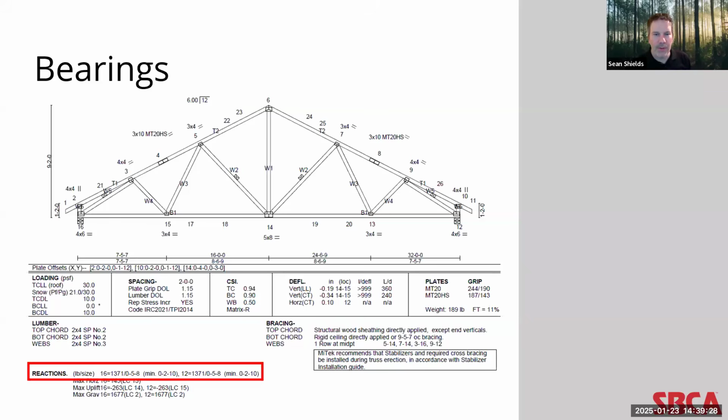And this is noteworthy, mostly from the standpoint that, let's say, for example, a wall gets a little out of alignment, and that truss heel isn't sitting completely flush to the outside edge of the top plate wall here. The installer on either end may look at that, and when the building inspector comes in, they can both pull out and consult the truss design drawing to look at and measure how much of the truss is sitting on that bearing area to determine whether or not it still will perform as designed.